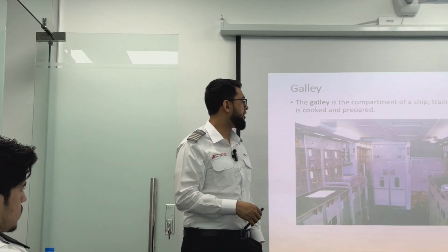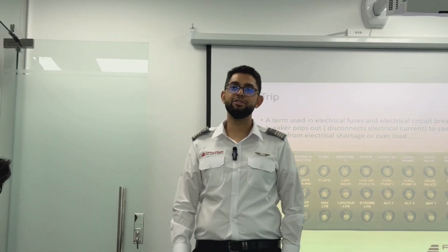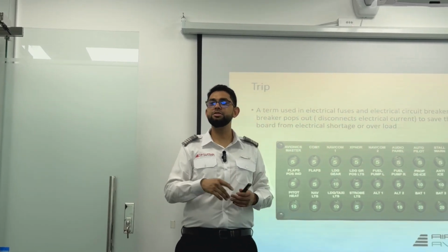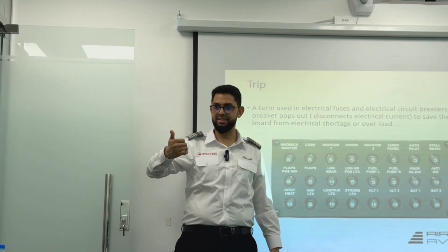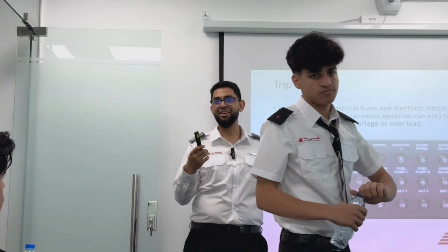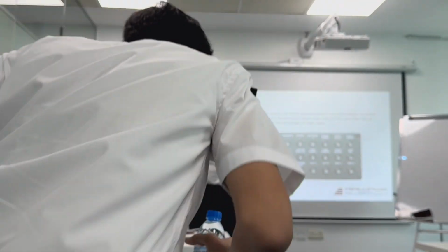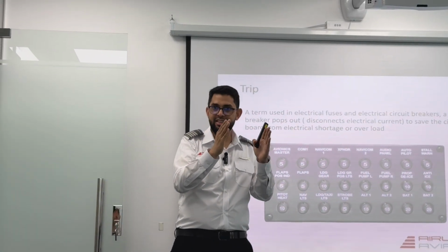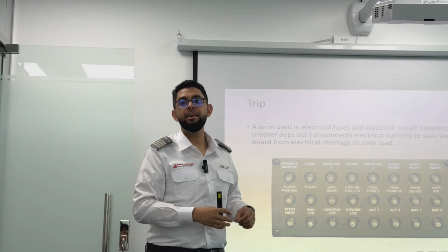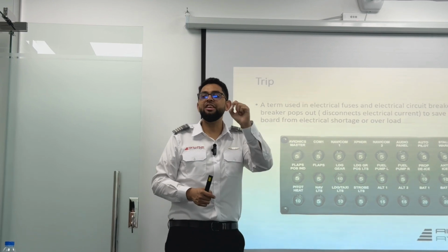So we're going to talk about short circuits, which is the reason why we have something called these trip meters or these switchboards, trip switches. These are very much similar to your houses and all of your buildings. If there's a short circuit in this room, the entire floor will not lose electricity, correct? In fact, it will not even shut down the electricity for the entire office. It'll isolate the short circuit to that particular room, and the trip for that particular room shuts down. Make sense? Similarly, there is a trip, which is a breaker switch, for every single instrument.